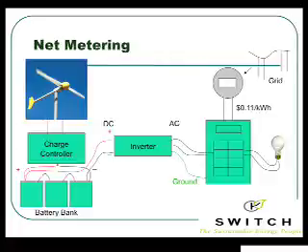So the wind power, is it DC or AC? Pardon me? The wind power? Is it DC? Well, it can be either. When it's made in the turbine, it's made in AC, a wild, uncontrolled alternating current. Then it's usually rectified, or changed over, into DC. And then you can store that in batteries and use it if you want. Or it can be changed back to AC in a regulated fashion so that you can use it for your appliances.